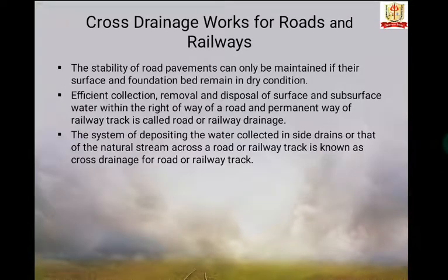Next is cross drainage work for roads and railways. The stability of road pavements can only be maintained if their surface and foundation bed remain dry. Efficient collection, removal and disposal of surface and subsurface water within the right of way of a road and permanent way of a railway track is called road or railway drainage.